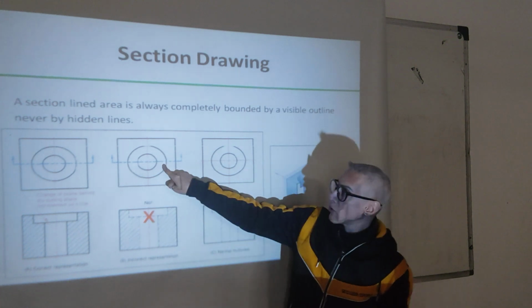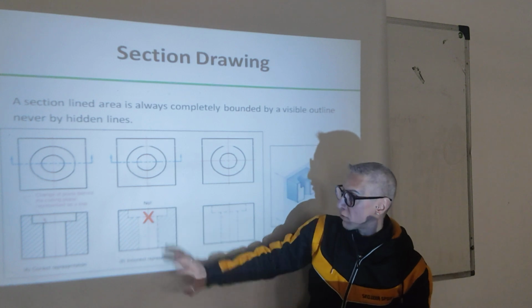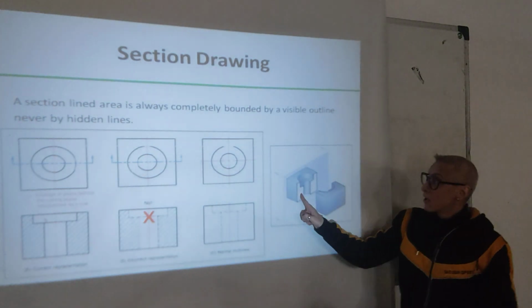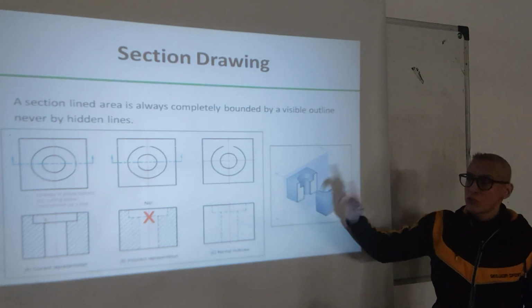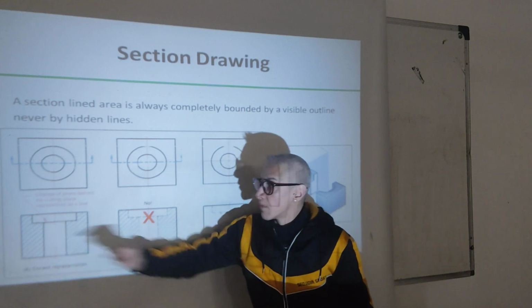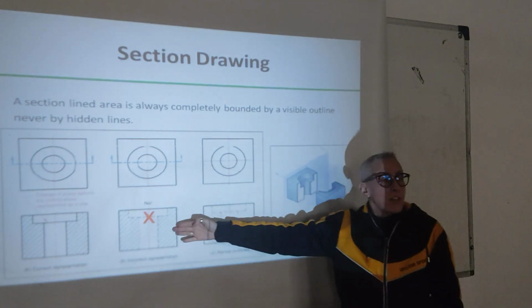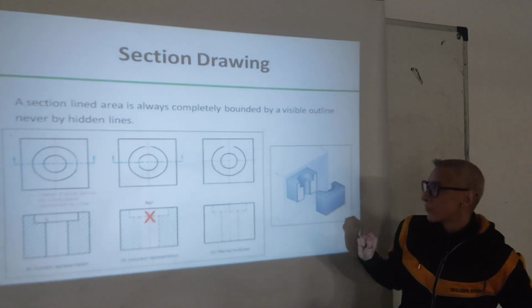We cannot have an object we're cutting, taking it down, flipping it, and then showing this as hidden lines, because they're not hidden. When you cut the object, you start seeing these lines as clear object lines. In the drawing, this can cause confusion, as I might think it is a hidden line. So the line type is very important.